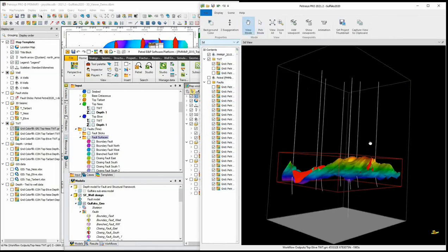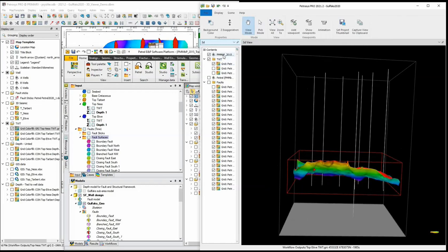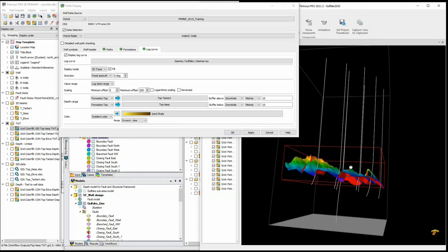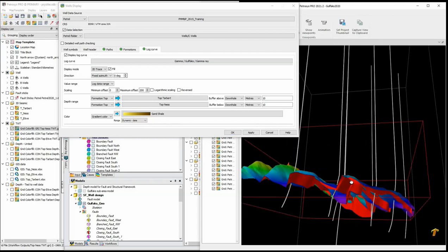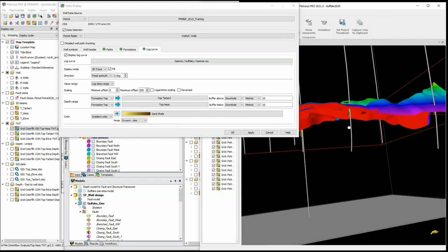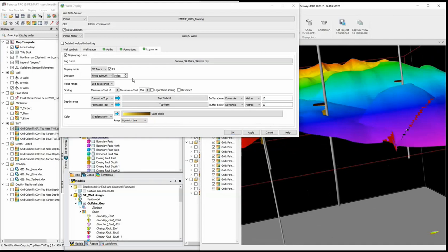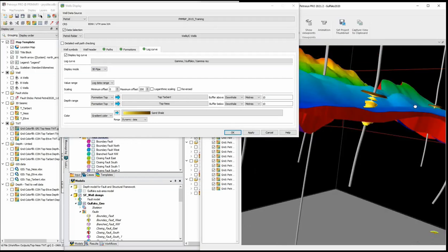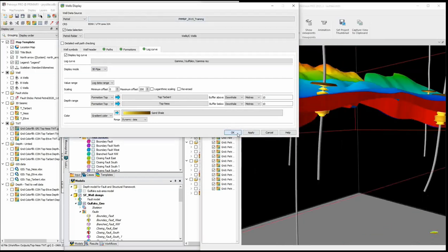So in our pan view, the mode will move back around, go back into our wells, and we'll finish off setting up our well log displays. We can go from 0 to 200, tick on have the fill, and click apply to that. Then you can see when we zoom in, and if we hold the control key, we can slide that up and down and move that around. You can see there that we have our log being displayed. If we change that to a 3D pipe and click apply to that, we then have our pipe logs being displayed in the 3D viewer.